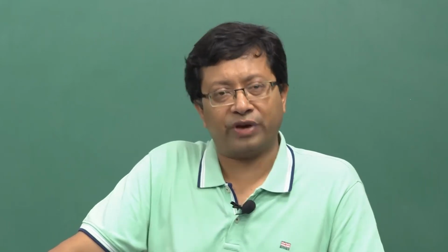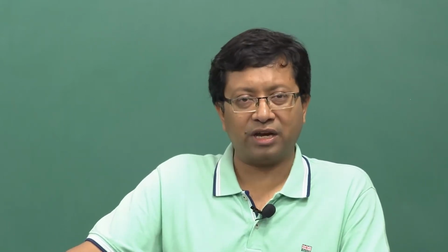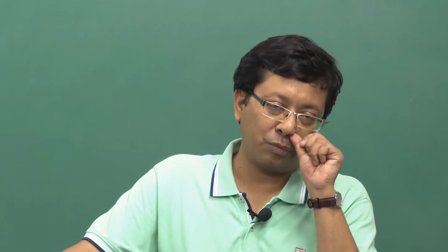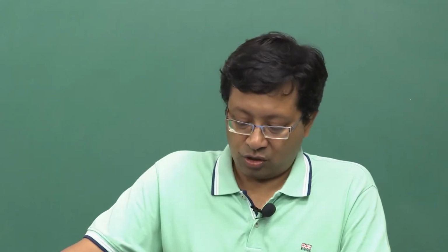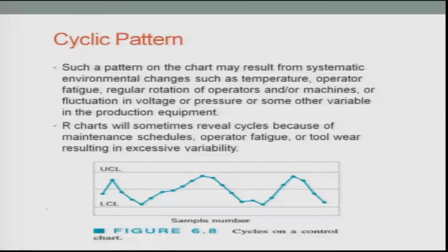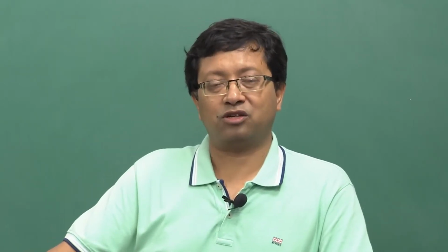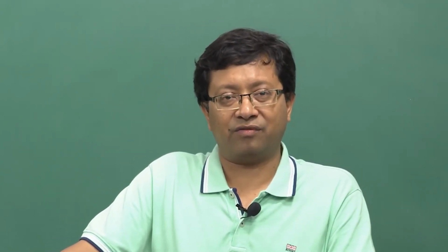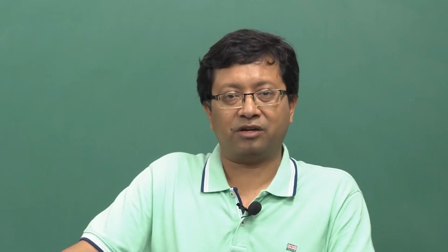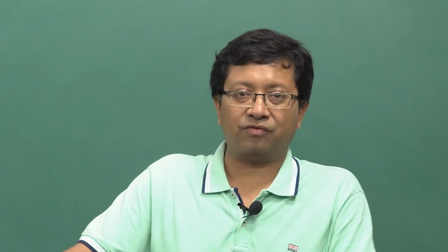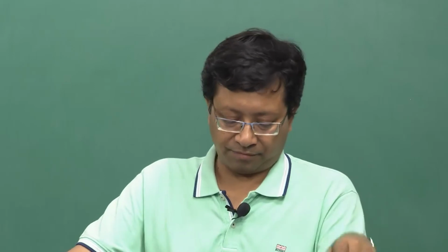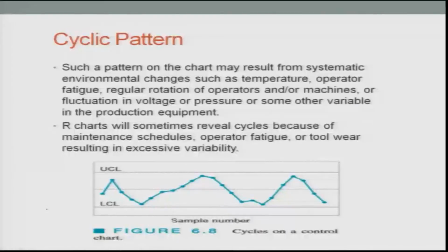But as there is wear and tear, depreciation, and the machine is being utilized day in and day out, obviously there would be some change in the variability onto the higher side. As I mentioned, operator fatigue is there. Tool wear can be one: in maintenance, when you check the machine, you change the tool, but as tool wear and tear is there, obviously it will have a negative effect on the machinability of the products, and the efficiency of the tool may decrease, which would not give you the right product. So, if you see the patterns,